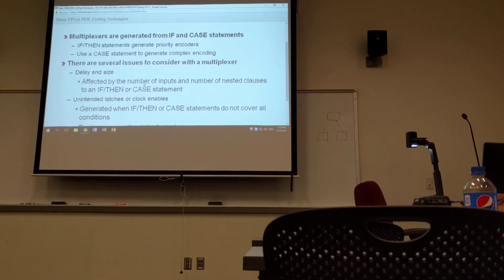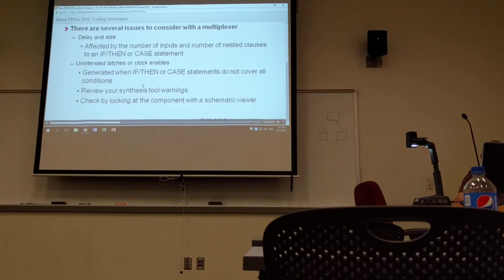You may have also heard that unintended latches or complex clock-enable equations can be synthesized when your if-then or case statements do not cover all possible conditions. Fortunately, synthesis tools warn users when they are building latches, but they do not warn when long clock-enable equations are being built. That is why it is important that you verify for yourself what is being synthesized by your HDL. To do this, the best tools provide schematic viewers that show when this is happening.